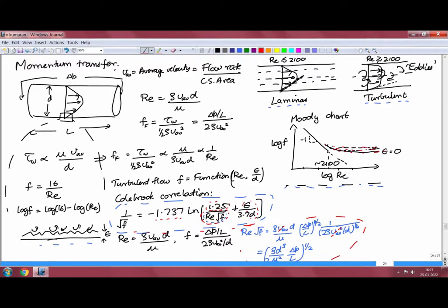There are large velocity fluctuations in the cross stream direction, and the transport of momentum and energy takes place due to eddies, which are parcels of fluid in correlated motion. And for a pipe flow, it takes place as the Reynolds number based upon the diameter and the average velocity exceeds about 2100. And we looked at correlations for laminar and turbulent flows.